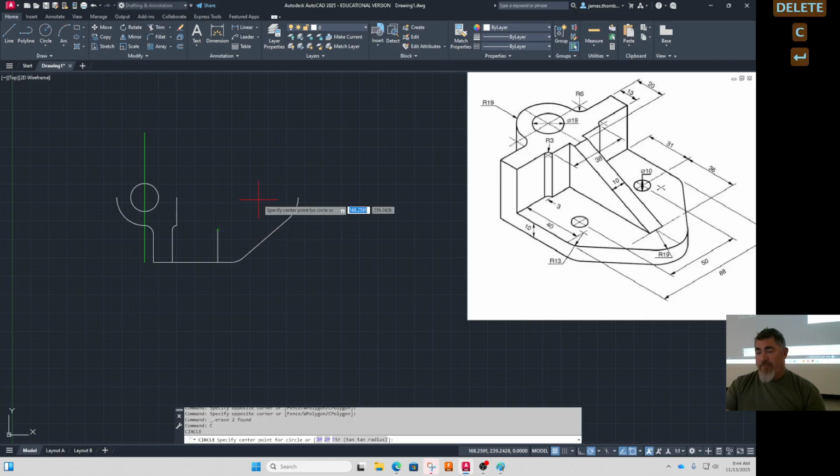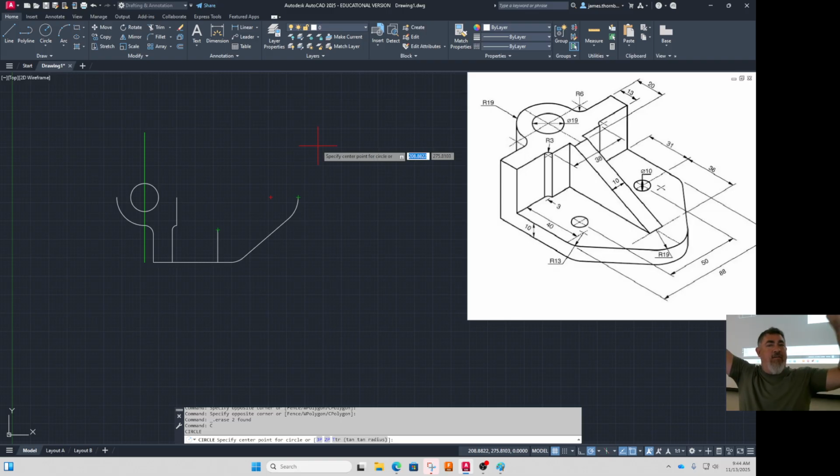So remember, if you just move your mouse over an O snap, you get that little plus sign, and then it's going to start tracking on your polar snaps from that one. And if you do another one, so now I've got 2 green dots, and tracking is activated. It's tracking based on all of the polar settings from both of those, and it also will now find the intersection because I have intersection turned on as an O snap, right? So if I just come down to where they're both tracking horizontally and vertically, it's going to find that intersection of where those two are coming together.